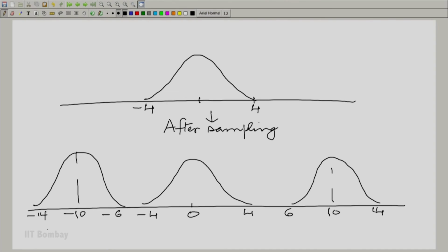Now, what we are saying is that the normalized frequency, this is of course the actual cycles per second frequency in kilohertz. And let me write the corresponding normalized angular frequency in red. So, at 5 we would have pi. At 4 therefore, it becomes 0.8 pi. This corresponds to 2 pi and so on.